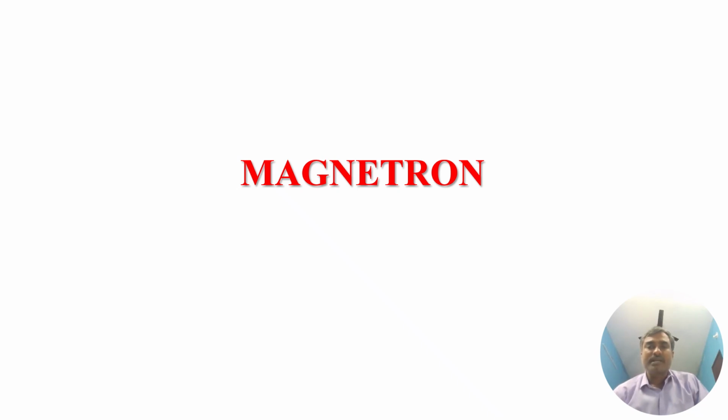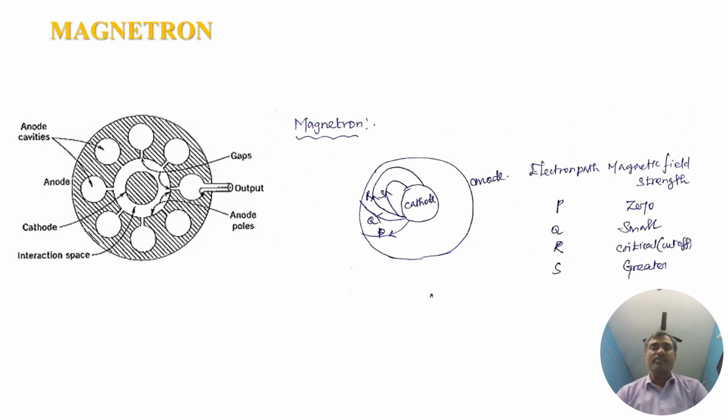microwave ovens as a microwave signal generator. Construction-wise, the magnetron oscillator consists of two cylinders, an inner cylinder and an outer cylinder. The inner cylinder acts as a cathode and produces the electrons. The outer cylinder acts as an anode, and the inner wall of the anode consists of cavities. In this, the microwave signals are produced. In order to produce sustained oscillation, a critical magnetic field must be maintained between the cathode and anode.